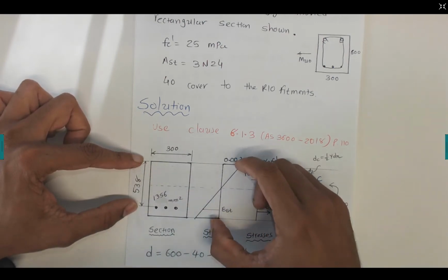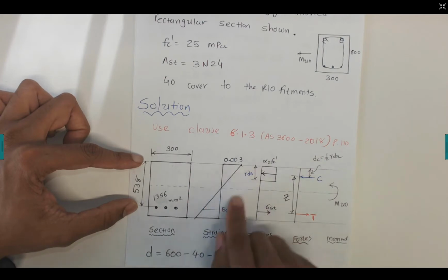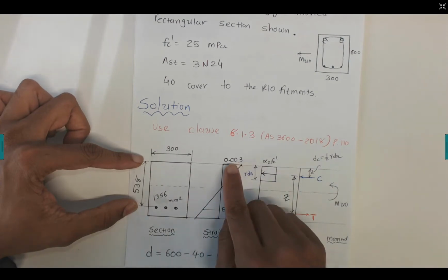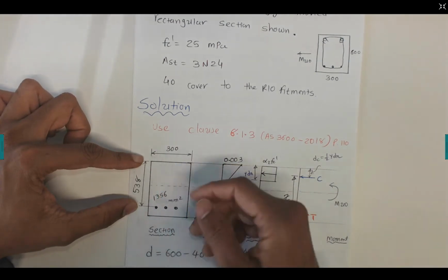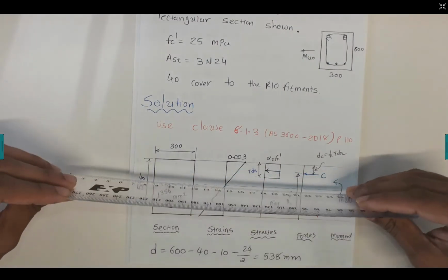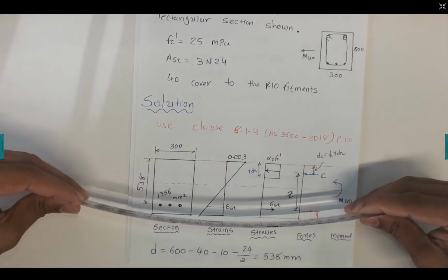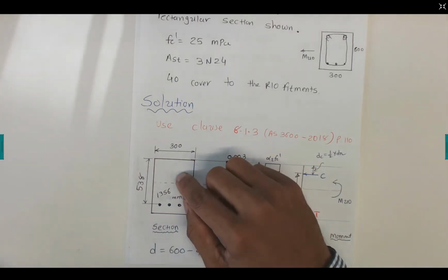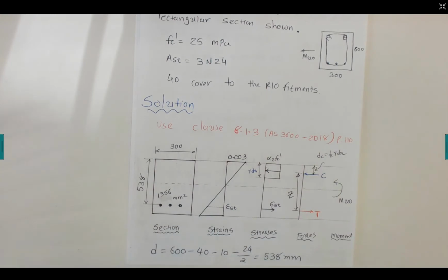Now in the previous video I drew the strain distribution for these sections. This is a linear strain distribution. The concrete is in compression. Now we are doing sagging. So for example, the beam is a rectangular beam like this, and we are compressing in the sagging moment. So in that case, we have compression on the top and tension in the bottom.